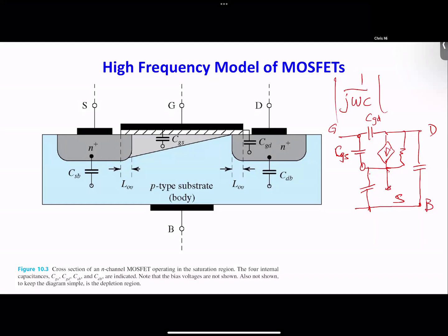The additional voltage is going to create additional current. So therefore, the original current over here is no longer accurate. Therefore, we're going to have another current, which is going to be gm times VBS. And this is gm times VGS. And VBS is calculated here. So we got this circuit over here.